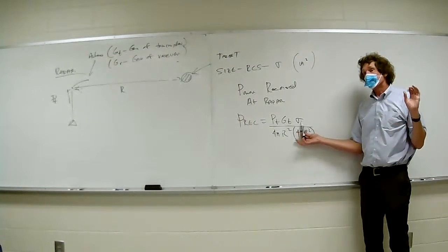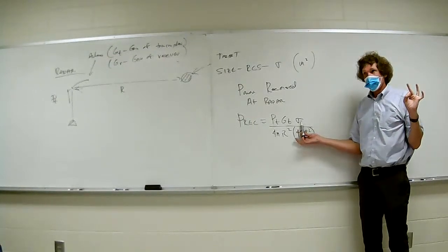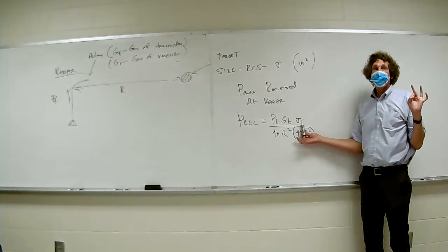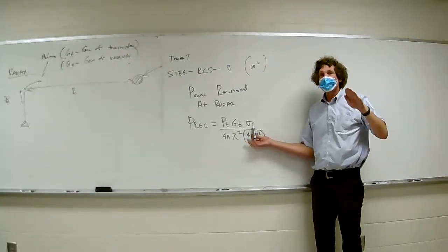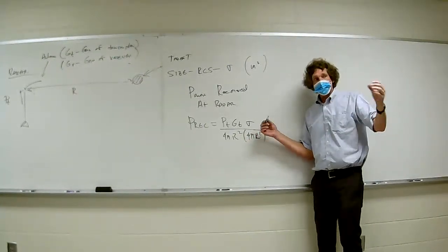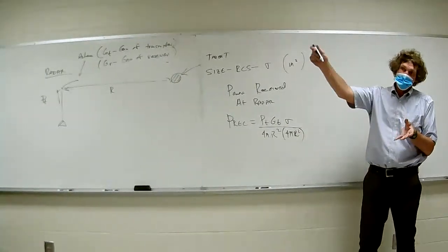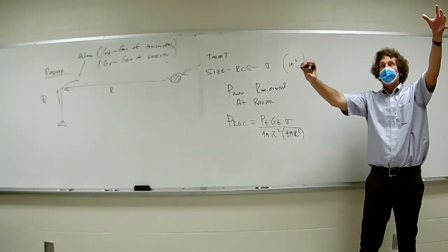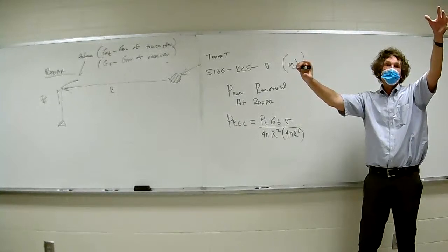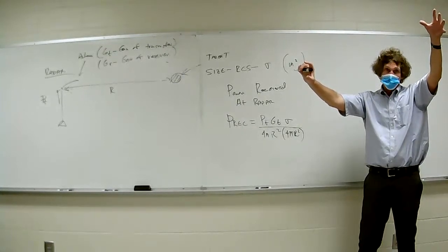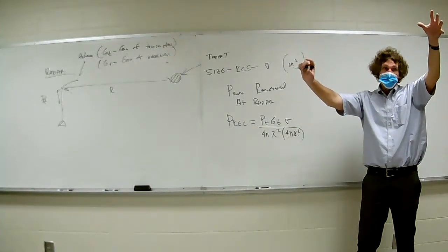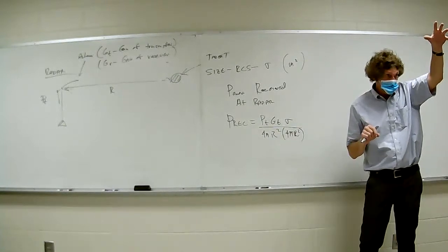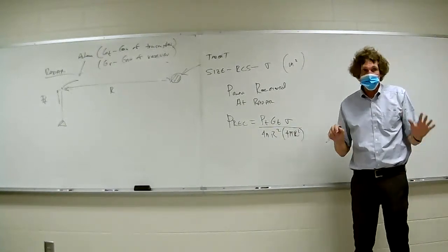This radar cross-section sigma will also be a function of angle. And what they do is adjust sigma so that if my transmitter is coming in at a certain angle, but the actual information I want collected is at another point, it's called a bistatic radar, then that sigma will have a different value. You're going to have to just understand. Think of it this way.